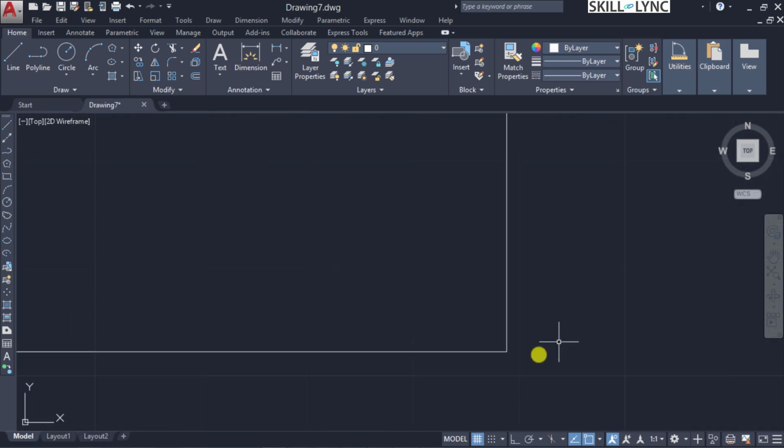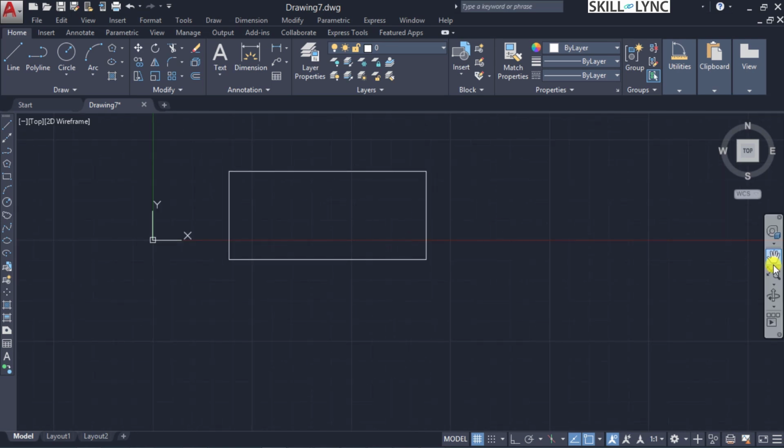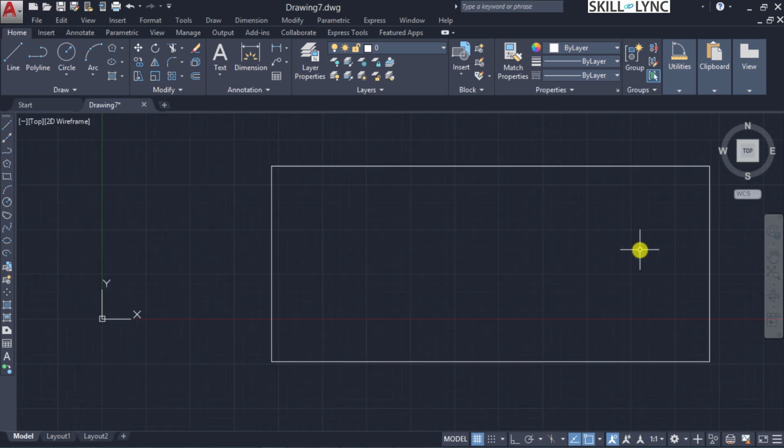That is, these four corners are sharp edges, so they might inflict damage or hurt the operators or the end users. This is a safety concern, and also a structural concern: these sharp edges become stress concentration points.